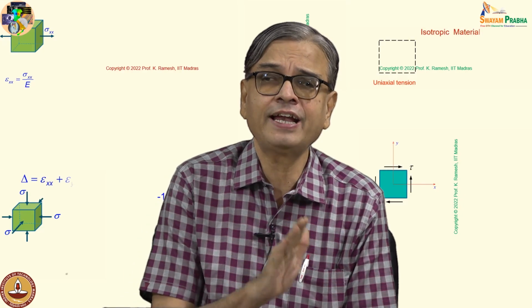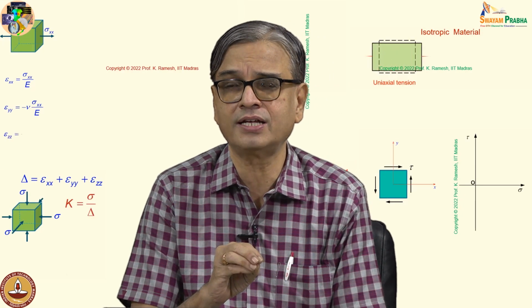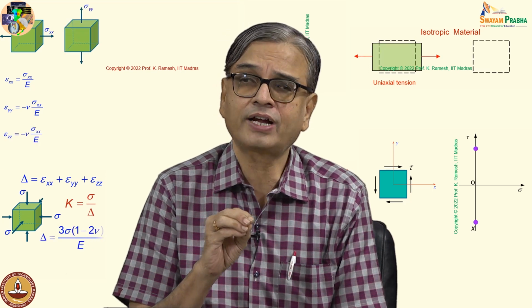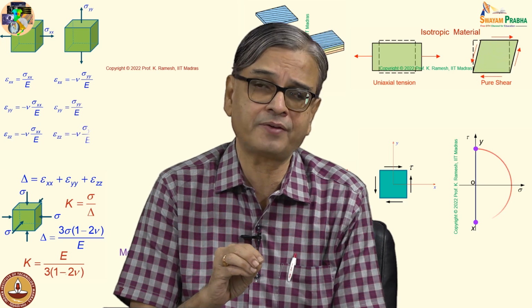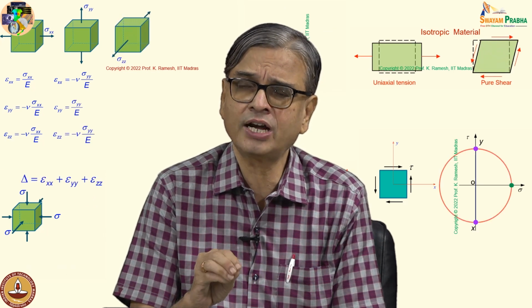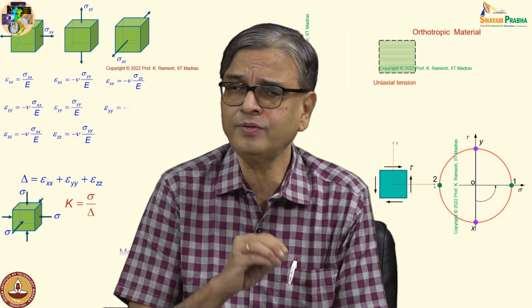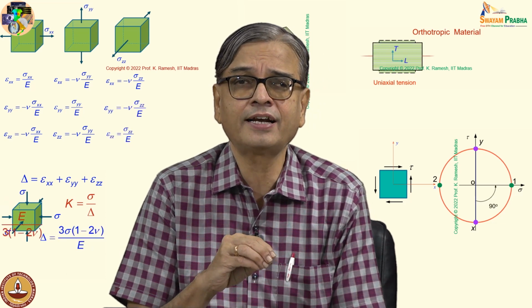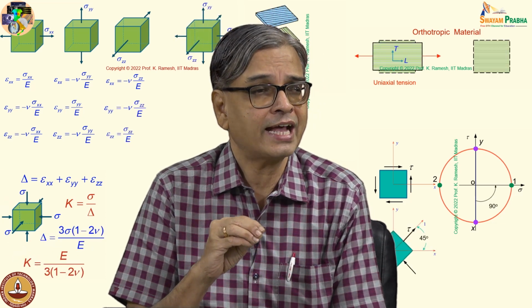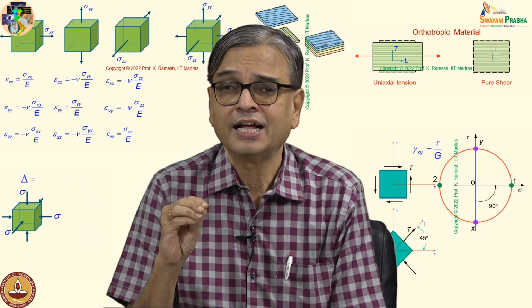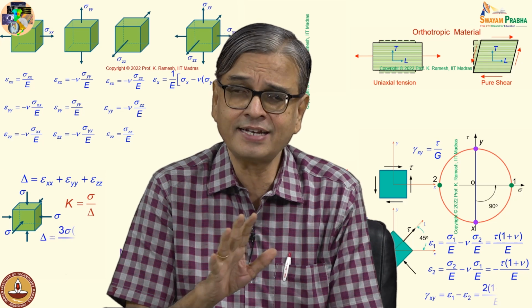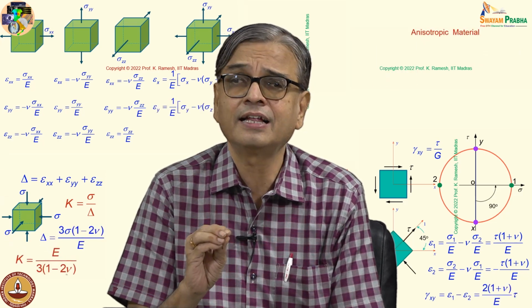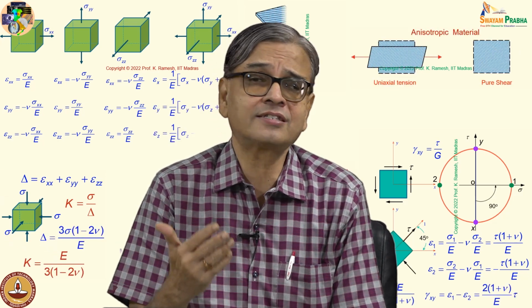So, what we find here is when we discuss shear modulus, when we look at bulk modulus, we have been able to establish a relationship between Young's modulus, bulk modulus and Poisson ratio. Similarly, an interrelationship between Young's modulus, shear modulus and Poisson ratio, and these interrelationships declare any two elastic constants are sufficient.